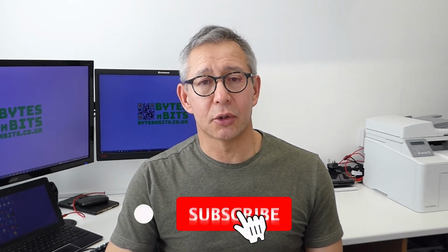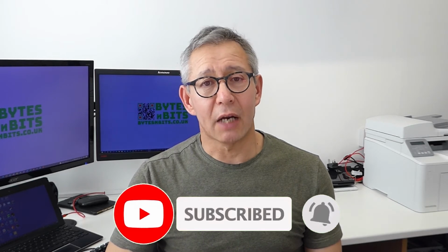There are a number of ways of getting sound out of your Raspberry Pi and especially your Raspberry Pi Zero. And in a previous episode I looked at using the analog sound output and recreating the headphone socket and then off into a loudspeaker. In this episode, we're going to try and get slightly better sound quality by using the Inter-IC sound system, or the I2S, which is a digital sound signal primarily designed to send signals around circuit boards. But we have that available on our Raspberry Pi Zero, and hopefully that will give us a bit of a cleaner sound. So let's find out a little bit more about I2S and then implement it on our Raspberry Pi.